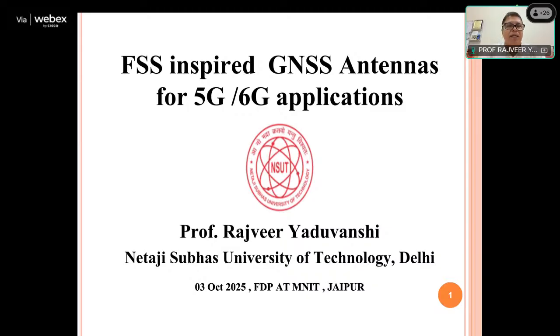In this NavIC antenna or multi-band GNSS antenna, we have used both. We have used the FSS structure to act as an antenna, as well as to act as an absorber. So I'll be talking about the theory, how these theories are applied, and how we have not only designed the FSS structure but used it to make the GNSS antenna using dielectric material.